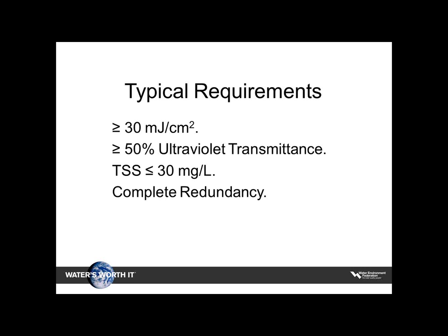So complete redundancy, again, what does that mean? Is it the banks? Is it the full channels? That's something you need to consider on this. And one of the other things you need to talk about is some type of backup generator, or at least to be able to handle the full load of UV disinfection at this point.